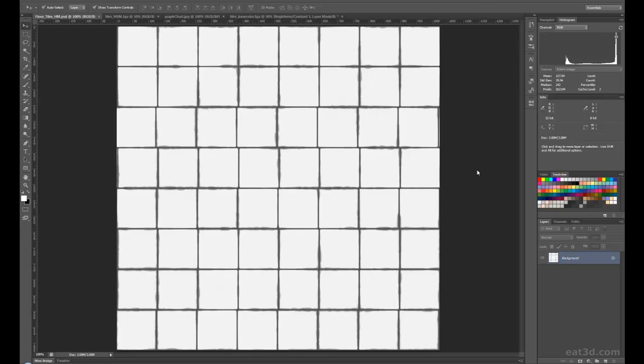I can either use a photograph to create a normal map, because what I want to do is create a normal map out of this, so that in the end it makes it easier to start doing the tiling texture within Substance Designer if you've actually got some sort of normal map there. So we can either change this height map directly in Substance Designer and change it to a normal map. So then straight away we've already got a normal map straight from this height map.